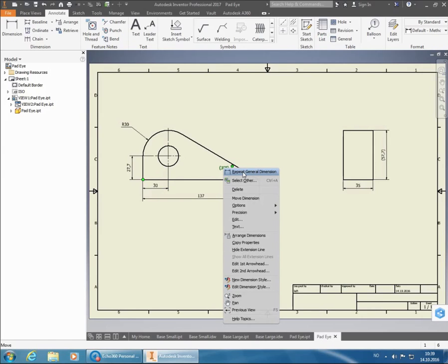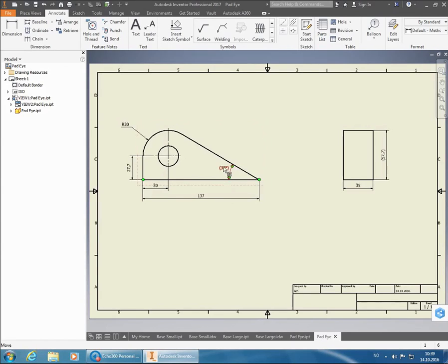We're going to go down to the options part. And then we can see we have quite a bit of different choices in here. The reason it's switching from 30 degrees to 150 once I move it to the outside is that we have a mark beside use quadrant. Because that means that it's going to give the dimension of that quadrant of a full circle. So if we remove that black check mark by clicking on it, now we can drag the dimension to the outside and it stays 30 degrees.